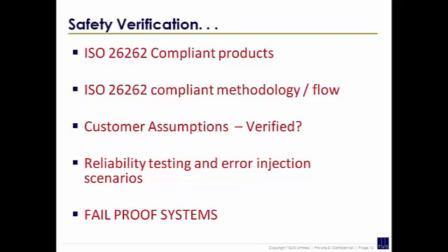Customer assumptions verified. This is one important point I wanted to highlight here. Sometimes we say we expect the customer to use it like this. The ball is out of our court now; we just said it and passed it on. But they are saying, when you're claiming that, have you verified that when the customer uses it like that, it really works? This is called customer assumptions being verified. So anytime we have a customer assumption in the spec, ISO 26262 comes and says, show us a test case which is verifying this. Then we have to show that test case.